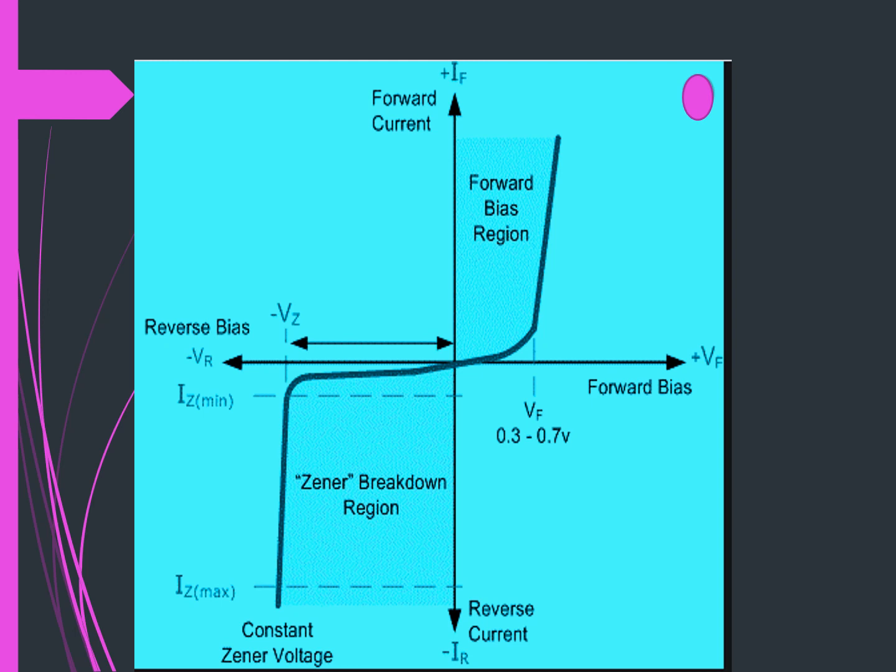Whereas in the ordinary diode or simple diode, which is not particularly doped to make it a Zener diode, the line is not vertical, it's a slanting line which shows that the voltage varies a little. Whereas in the case of a Zener diode, the line will be very much straight, which shows that the voltage is constant. That's why the Zener diode is used as a voltage stabilizer.